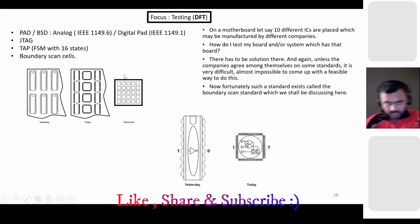Okay, so now we'll focus more on testing from here onwards. Let's go to the pad and BST, which we discussed in the previous slide. Just remember the top level block diagram where we had the pad and pin muxing and compression, because I'll be discussing around that. As I told, for analog pads we have the 1149.6 standard, and for digital pads we have 1149.1.